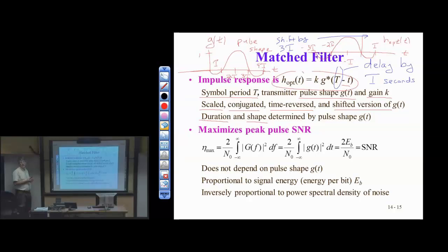That's it. It's that simple. Now the phase is going to be a little different because we've delayed it a little differently, but it's still a linear phase. If we delay by a constant, we just change the phase by a linear factor. So we're not distorting the phase other than linear phase, which is very easy to undo.